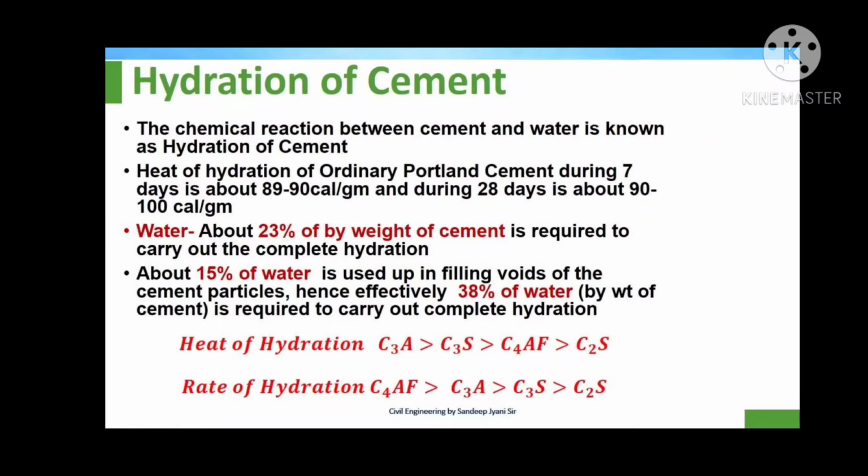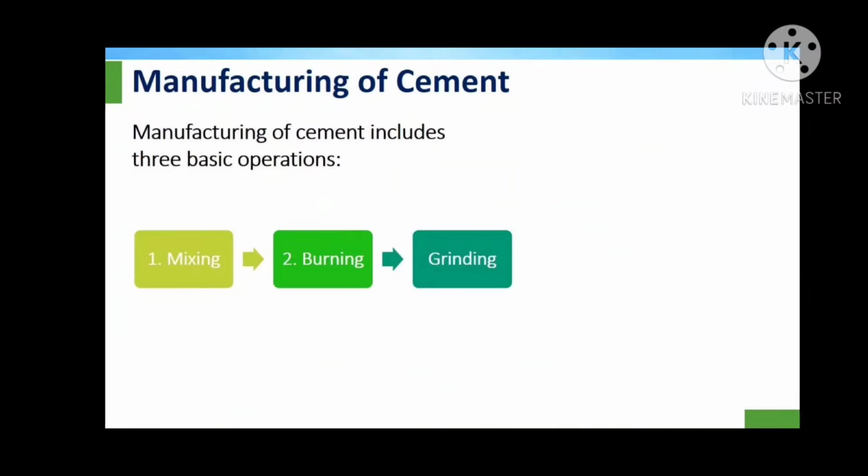Heat of hydration: C3A greater than C3S, C3S greater than C4AF, C4AF greater than C2S. Rate of hydration: C3A greater than C3S, C3S greater than C4AF, C4AF greater than C2S.